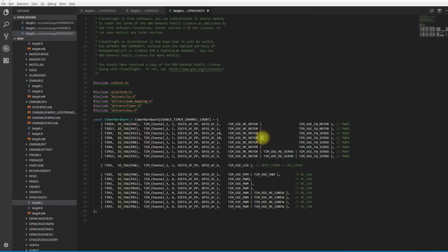This is why, even if you, for example, have a quadcopter and you are using only 4 first motors, motor 5 and 6 have to stay unused because they are sharing the same timer and frequency, the ones that before them, and only PWM 7 or 8 can be used as a servo in case of a multi-rotor.